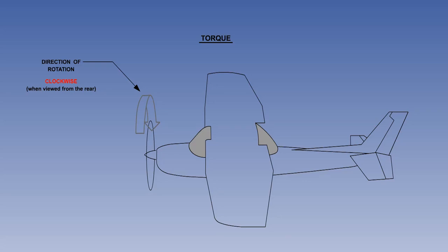We have learned that a propeller generates thrust by accelerating a mass of air rearwards. Unfortunately, a rotating propeller will also create significant yawing, rolling and pitching moments. These moments give rise to 4 turning effects, which must be anticipated and compensated for by the pilot. The majority of piston engines fitted to single-engine light aircraft rotate clockwise when viewed from the rear. This is called a right-hand propeller.